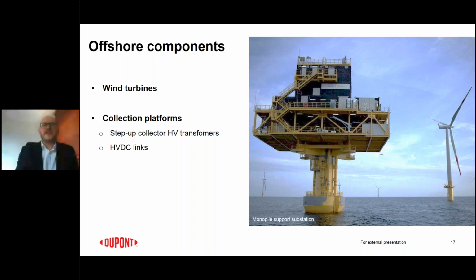Like you can see on the chart, the entire substation with the heavy transformers inside, on the onshore. And this is one of the critical components for the wind farm connection to the grid. And if the distance is long enough, if the power is large enough, this platform may not be limited to the AC collector and the transmission transformer, but could extend to the HVDC link. And then we have the HVDC converter transformers to be involved in the installation.